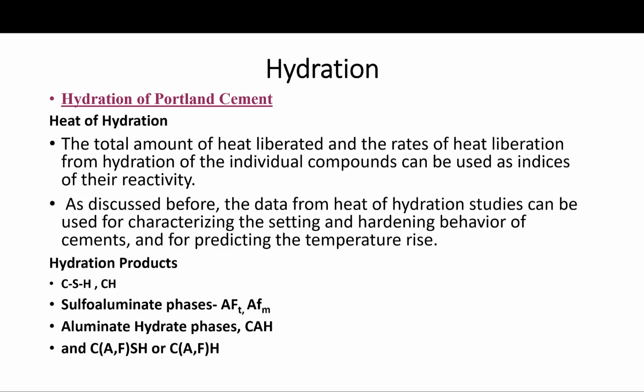So the total temperature rise is important, as discussed above, and as we mentioned during the talk about the cement types and their uses. If you remember, the ASTM specifications put limits on the cement composition and or on the amount of heat of hydration.